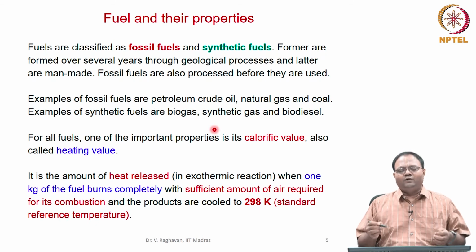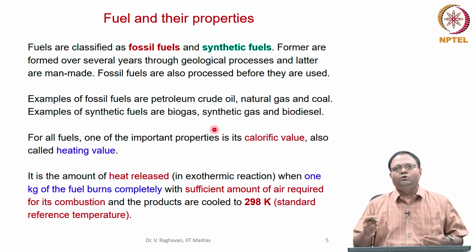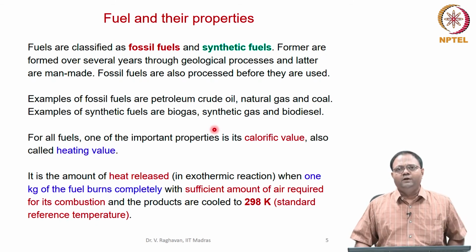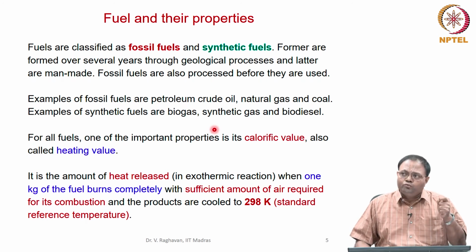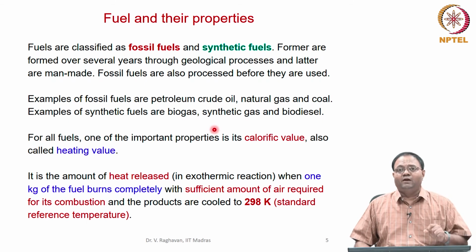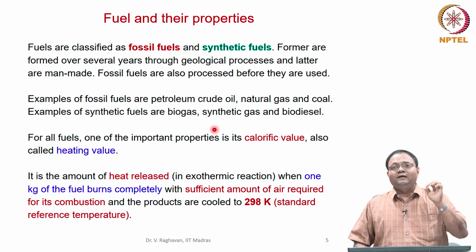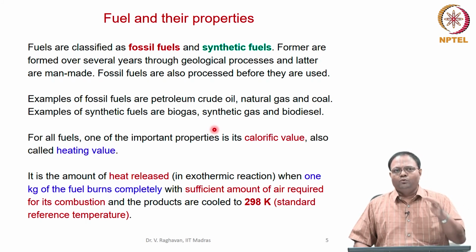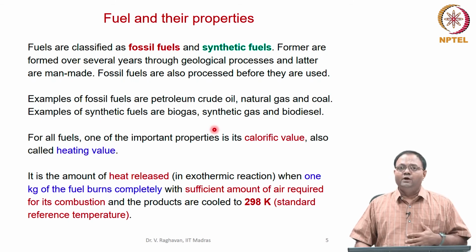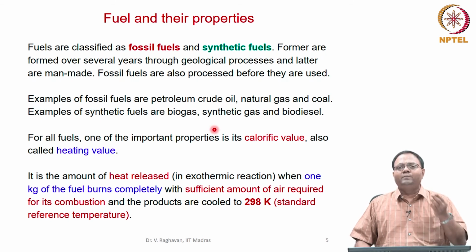So in recent years we have gone to what is called clean coal technology. When you want to use coal, which is abundantly available, we need to understand how it can be converted into some cleaner fuels. As I told you, the solid fuels are not very clean, they are heterogeneous in nature, basically because of the mineral content, which is called ash, and also because of sulfur and moisture.